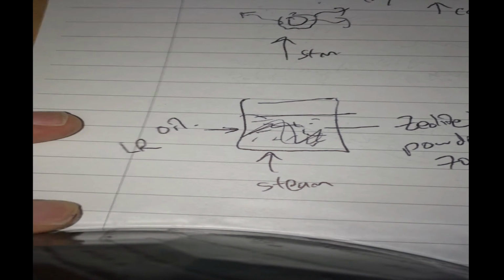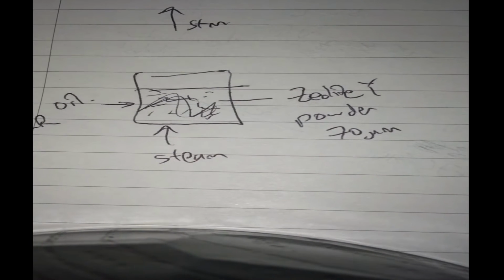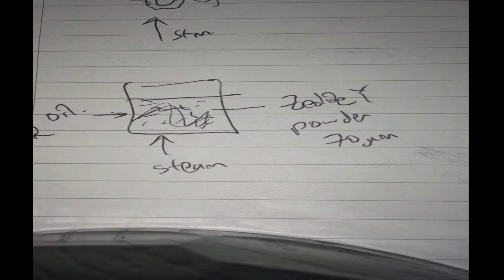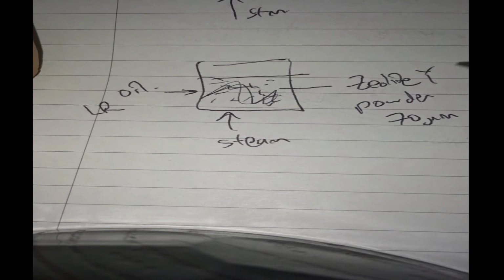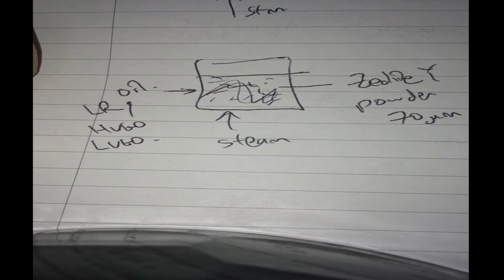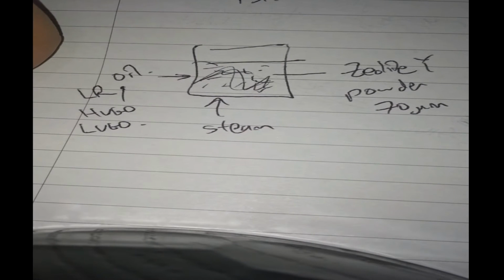You can even put short residue there, but that's going to severely affect your catalyst life for the above-mentioned reasons, because most of the metals will be trapped in the asphaltenes. Alright? So usually there'll be long residue or heavy vacuum gas oil, light vacuum gas oil, stuff like that. You can put it into your catalytic cracker, and then what happens?